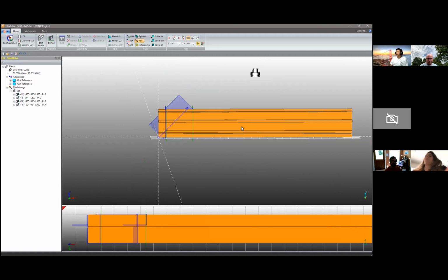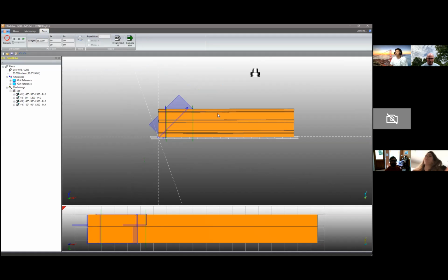So if this piece is small, for example, if this piece is only 35 inches, it doesn't allow us to clamp because we need at least 12 inches per clamp over here and here. But the machine will give the boundary around 6 inches away from the blade diameter. In here, it could be this cut like this.